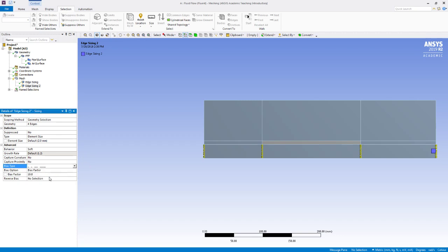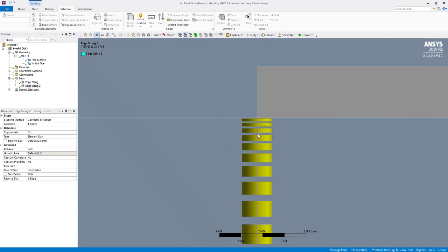And then there's just one of the 3 needing reversing, this one. So we'll have nice small elements up to the boundary. We might even reduce the element size a little more to 1. There we go. Nice small elements near the edge.